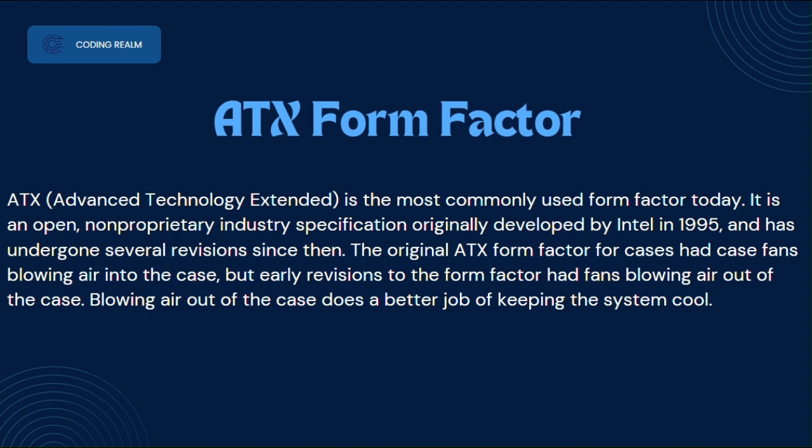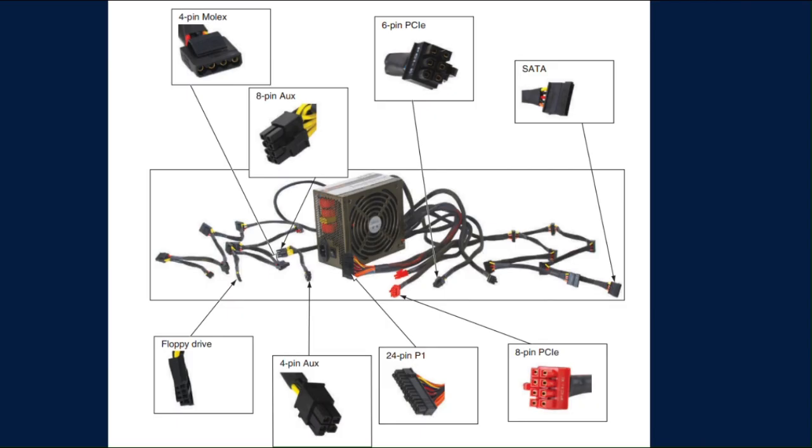The original ATX form factor for cases had a case fan blowing air into the case, but early revisions to the form factor had fans blowing air out of the case. Blowing air out of the case does a better job to keep the system cool. This is the importance of the ATX form. And this is the ATX form in our computer.